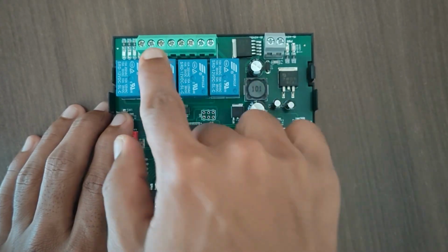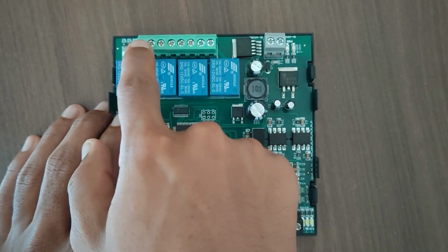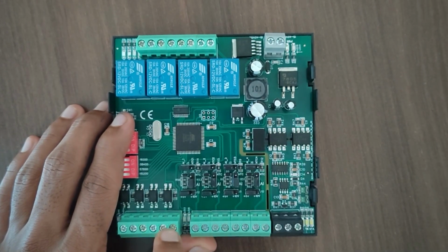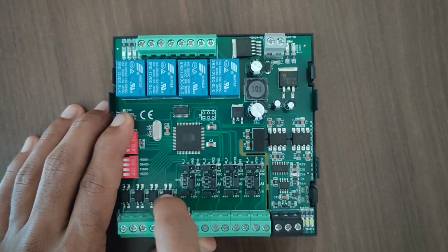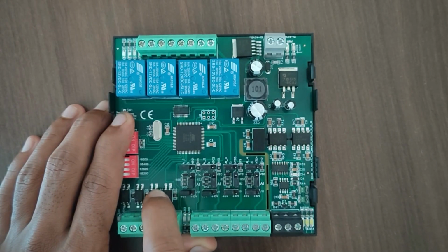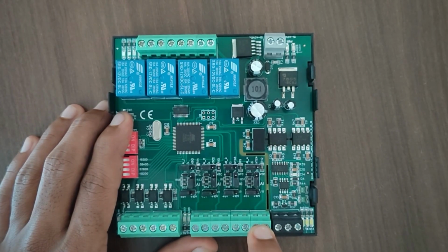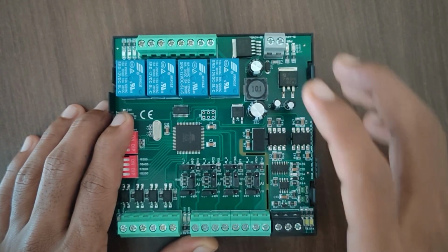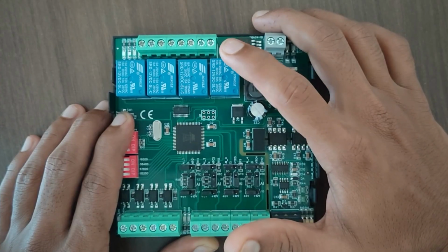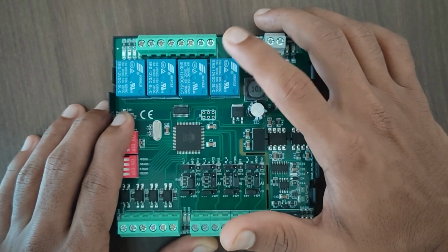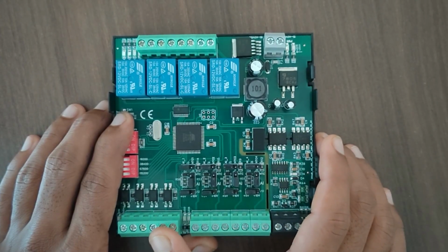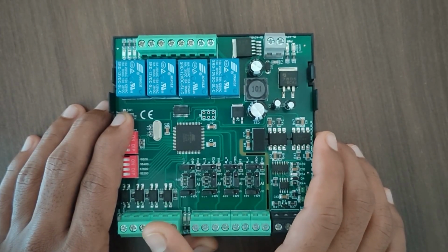For this board, here we have the DO part, that is the 4DO part, which is operated through the relay, and here we have the DI part, which is operated through optocouplers, which support up to 80 volt, and here we have the 4 AI channel part and also 4 NTC. In the DO part, the user can connect motors, switches and relays. For the DI, the user can connect sensors, relays, switches.